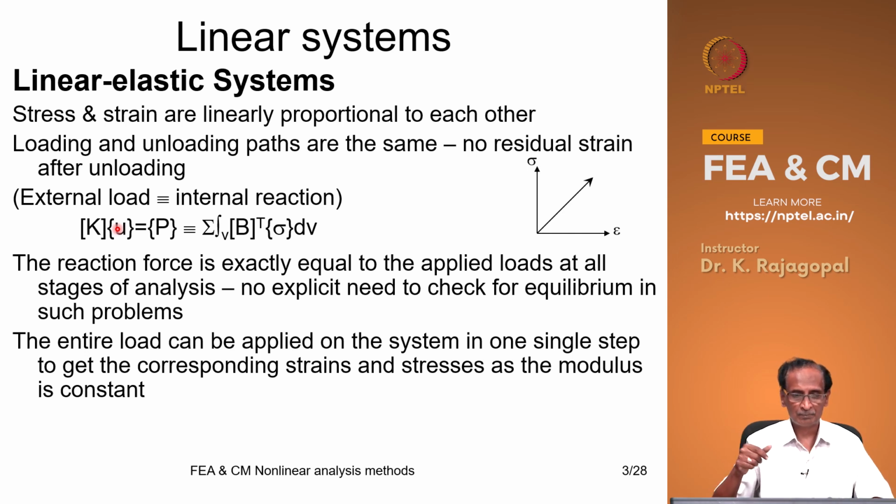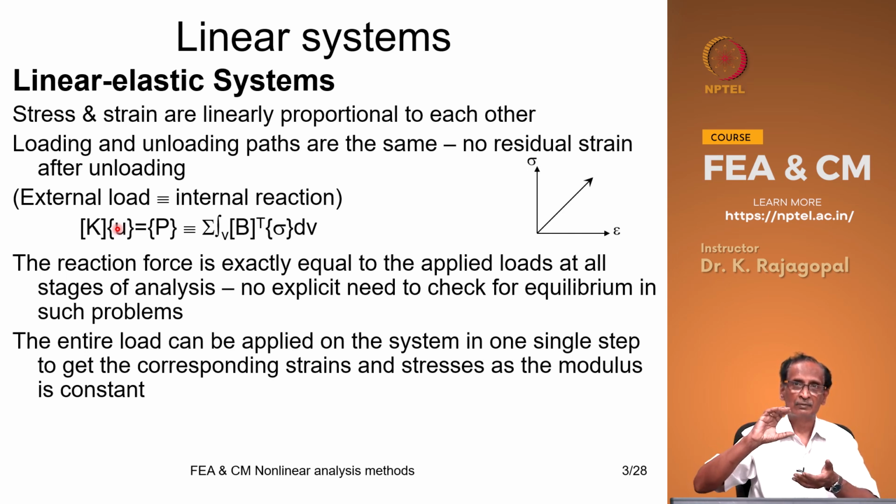of applied forces. And in all finite element analysis, you can either apply a force at a degree of freedom or a displacement. You can apply only one of them, and although I am saying we apply the force, we might as well apply the displacement, because as we have seen earlier with the example of the two blocks attached through an inclined joint element, where we applied equal vertical displacements at the top and then measured the reaction